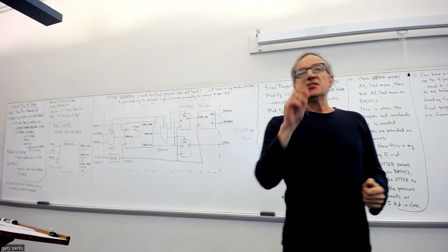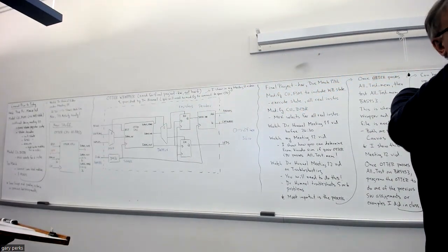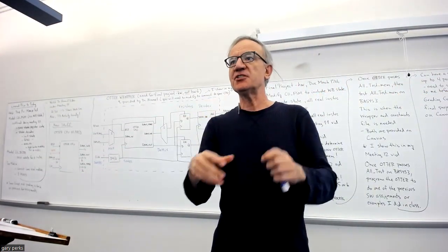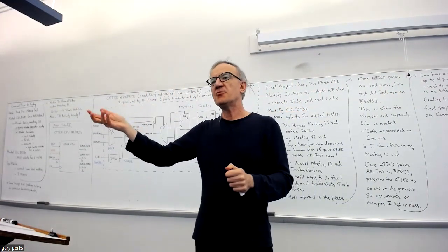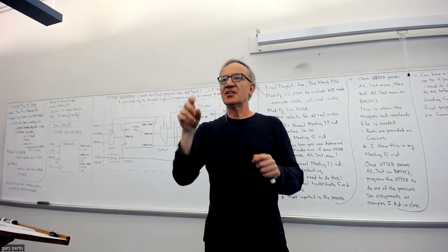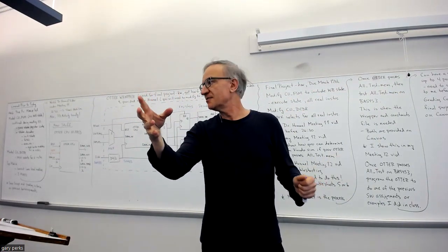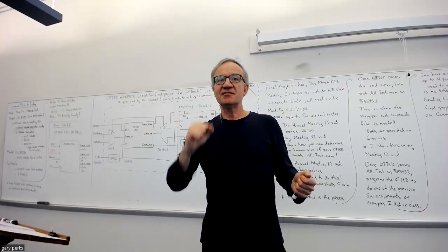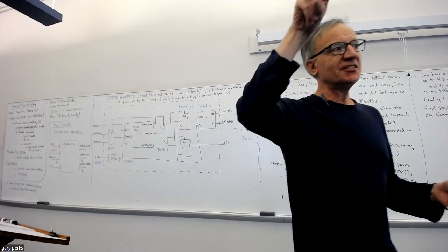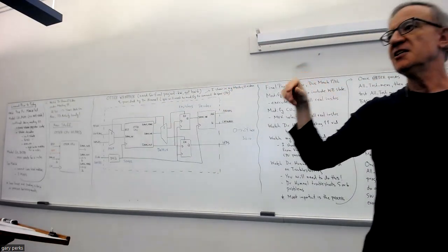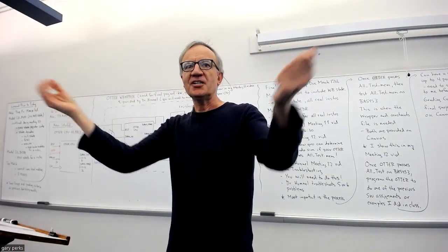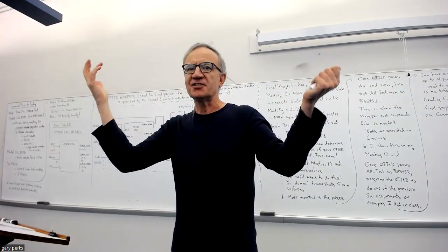Now, you'll have to add a delay, whether the delay is on the input side if you're using the switches, or on the output side. Say you're calculating a difference and outputting it to the 7-segment display, and then doing another difference and outputting it again, like you did for software 5, when you're doing the differences between the two sequence numbers. You would have to put a delay there. Otherwise, when you look at it, it's just going to be gibberish.